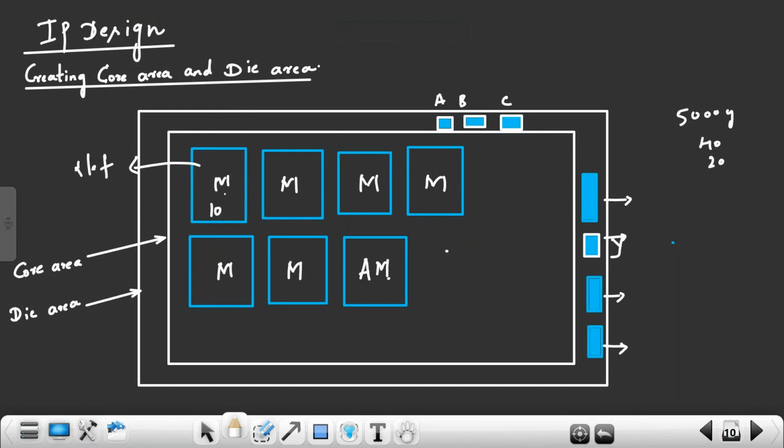Effort of designing a macro is reduced. That is called macros. These are called hard macros because I have only layout information. You can even directly purchase RTL as a macro. That is called a soft macro, where you know what is the functionality inside the macro. That you'll understand later in depth, right?